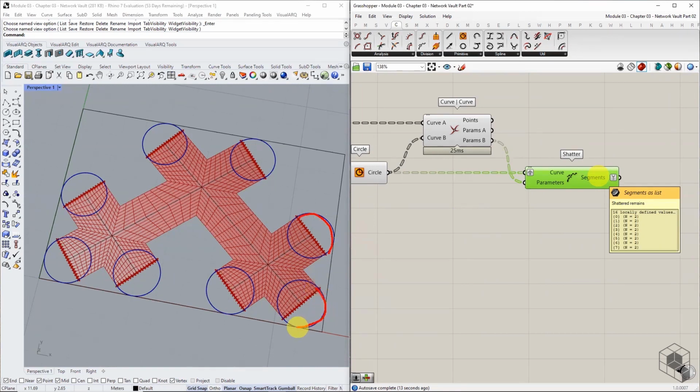We can pick a point on the curve, and check whether it falls within the trimmed surface. Curves that are towards the initial line network will always have a point within the trimmed surface. The same isn't true for the curves pointing away from the surface, except for the endpoints. So, choose any point on the curve other than the endpoints.